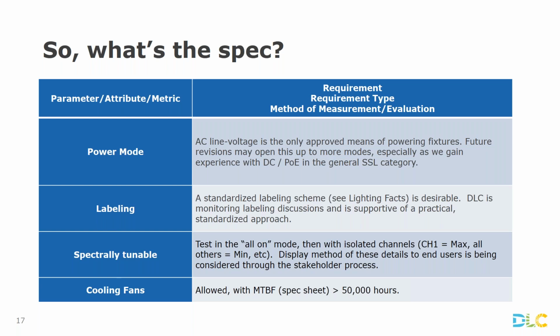Finally, the last specification that I've highlighted in this table is cooling fans. These are cooling fans that are built into the light fixture to help keep the power supply and LED device temperature within acceptable parameters. As I alluded to before, thermal is usually the big single reason that causes end of life for these products. And so, especially given the small physical footprint, if you want to avoid shading, for example, in a greenhouse, combined with the high power and high flux, does create a pretty challenging thermal environment for these